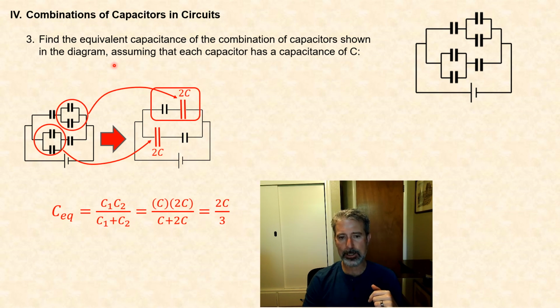So I can, once again, replace those 2 capacitors with a single capacitor having a capacitance equal to the equivalent capacitance. I'll just tell you that if you take 1 over C equivalent equals 1 over C1 plus 1 over C2, and solve that, this is a nice result: the equivalent capacitance is the product divided by the sum. This is only true for an arrangement of 2 capacitors in series.